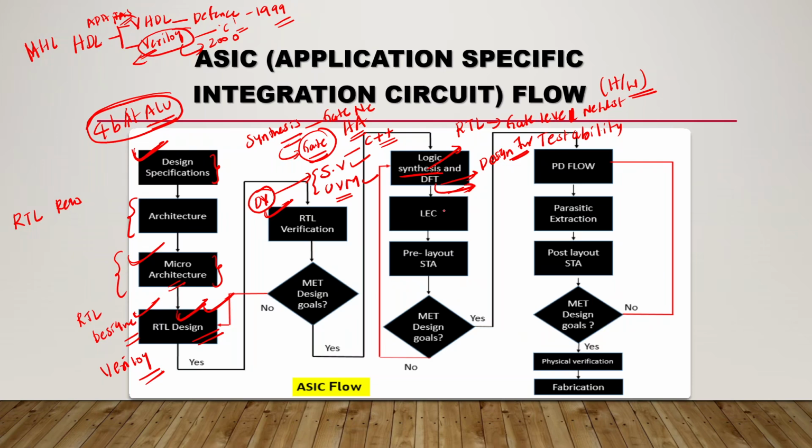Next there will be LEC, and, as I told you, pre-layout STA. STA is static timing analysis. In static timing analysis you deal with timing parameters like setup time, hold time, and delays, that is, what the delays in the modules are. If the design goals are met, it goes to the PD flow.